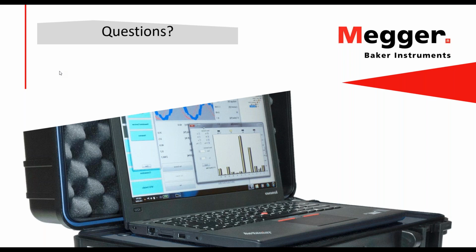You can do comparisons between the voltage injected into a VFD and the voltage that the VFD is supplying, between the currents that go into the VFD and the currents that go out of the VFD. You can find problems in the motor provoked by the VFD, and you can also find problems in the VFD itself, given the capabilities that the device has. So to answer your question, yes, it can definitely be applied to motors controlled by a variable frequency drive.